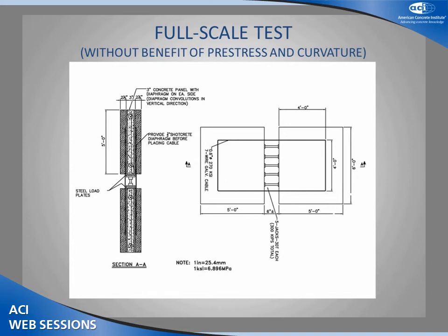If you want to use an analogy, when we have a circular column wrapped with spirals, it provides excellent confinement to the vertical rebar. And the ductility of a spirally reinforced column is very well known. But that is missing here, which is going to be there in a real case situation. The third thing is, we held the diaphragm in vertical position and poured concrete. So the liquid pressure of the concrete tends to push this diaphragm away. In a real life situation, we are putting the diaphragm in horizontal direction and pouring concrete.